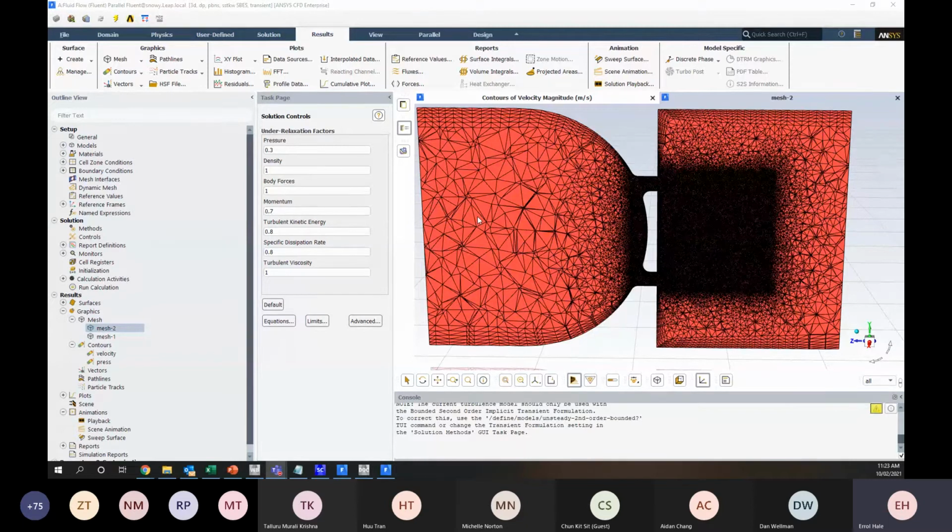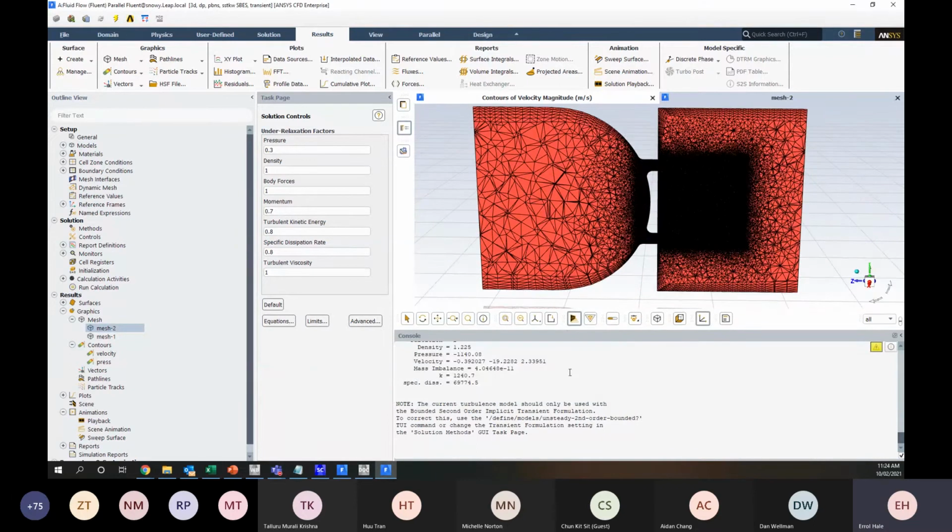200 does seem really high, and it is just a default to use when you are setting up your simulations. You can reduce that quite drastically, but for some steady state solutions, 200 can be fine, very case specific. When we're doing transient simulations, it can be more important to have low Courant numbers, and those can be assessed after doing the simulation and then maybe changing the time step. And once again, a lot of these things are very case specific and require a bit of trial and error.